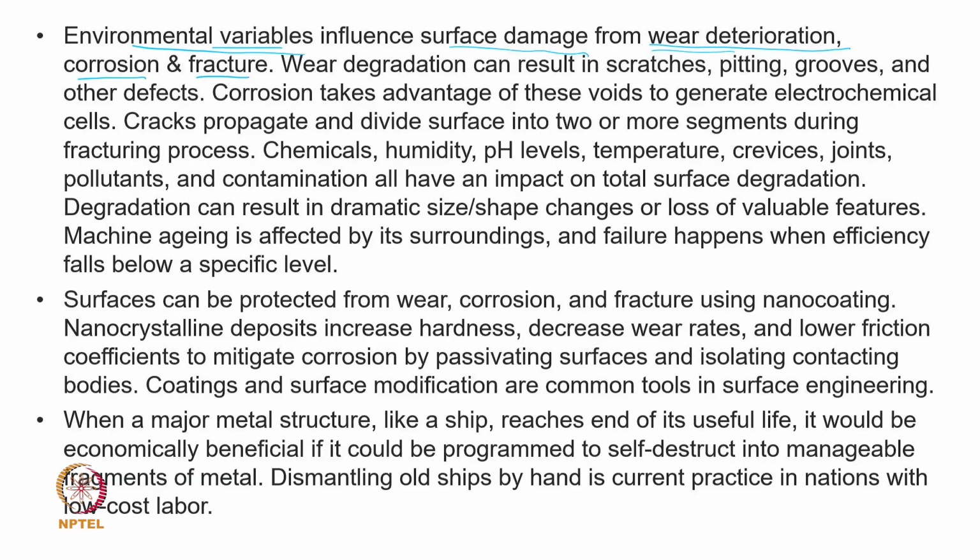So, now I am trying to connect them sequentially. Wear degradation results in scratches, pitting and grooves, or maybe other kinds of defects. So, wear is creating problems like this on the surface. There may also be fabrication related problems, but because of the deformation, some other process, or the relative sliding, these kinds of scratches, pitting or grooves can be cut on the surface.